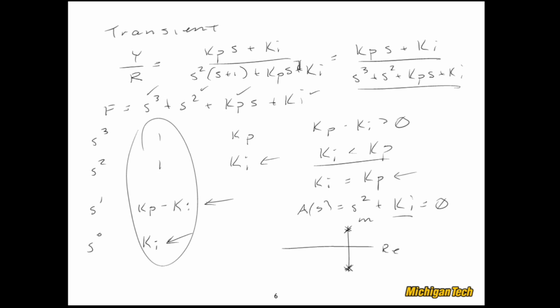So now we see that what's happening is that the closed loop poles are heading off this way as Ki becomes larger than Kp. Ki less than Kp, our closed loop poles are over here somewhere. Ki greater than Kp, they're over here. So what this tells us is that if we get too large with Ki relative to Kp, the system goes unstable. So the basic effect of increasing Ki for this particular plant, and for a lot of systems, is that it can lead to instability. And it can make the step response, for instance, faster than what you would get with just having proportional control.